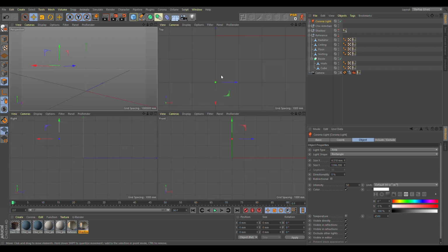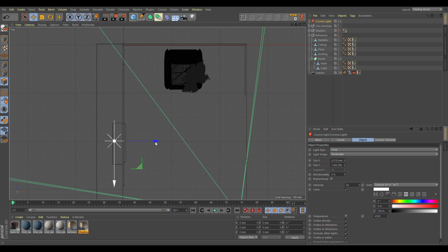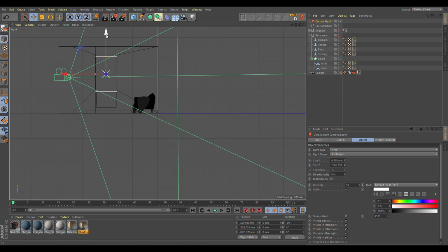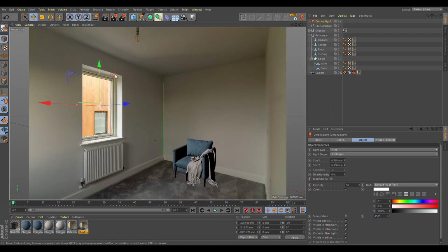Now we just want to snap it to where the boolean is, and have it fit in the right coordinates. So I'm going to drag it up to the corner, copy the x, and make sure it's in model mode so we can see the position, and it's moving on the z-axis. I'm going to snap that, and then in here do minus, paste in that size, divided by 2, and that will snap it to the middle. And then the same with the y. I'm going to copy the y, and then in the y, minus, Control V, divided by 2, and that's going to put it in the exact position of that window.